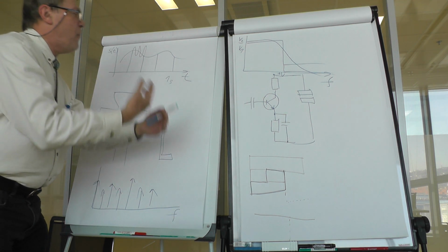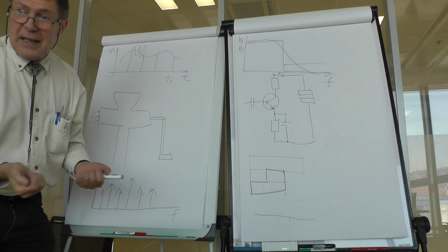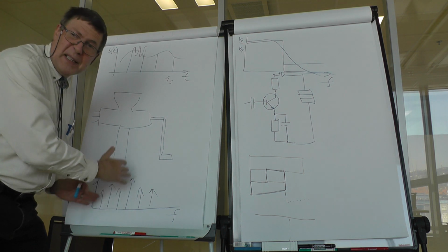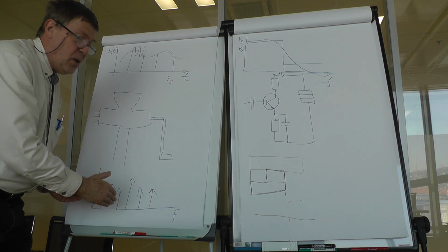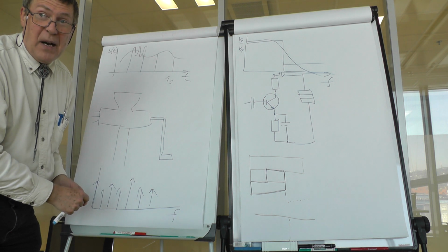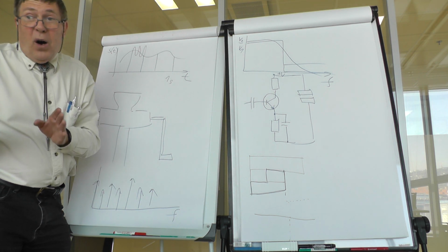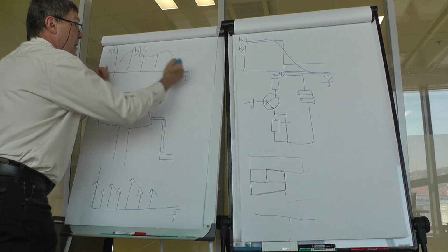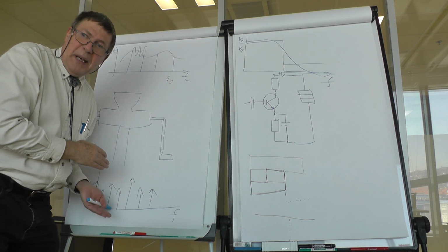So if I make 4 times more samples and average 4 frequency components at the output as to the magnitude, I can get only 25% maximum error. Yes, that's a maximum error. If you are only slightly wrong with the sampling time, the error would not be as high.